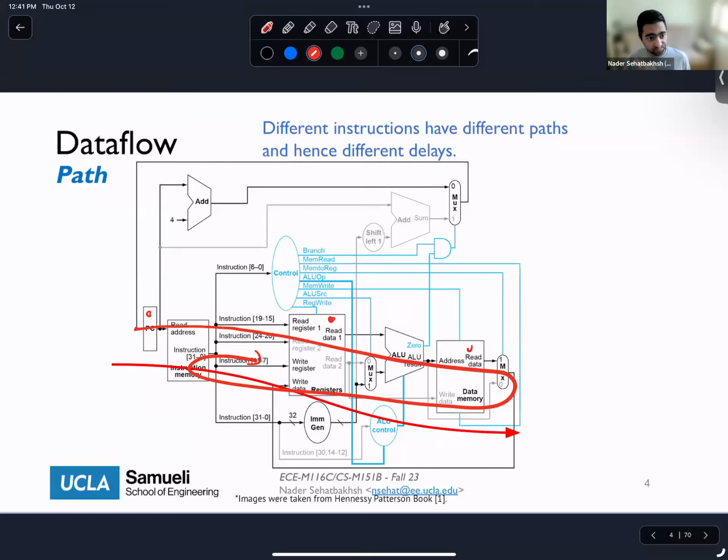is the time for my clock cycle, okay? Somebody asks, if the cycle is not close to the delay time, is there a risk of garbage values replacing the settled values? Yes. So if the cycle time is smaller than the maximum delay, then some of these units haven't settled yet, so you're going to read garbage at some point. So you're going to have correctness issues.